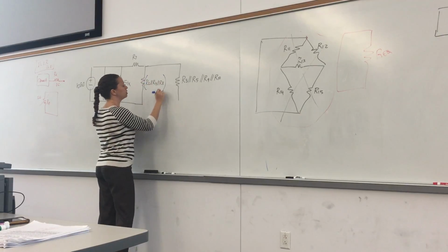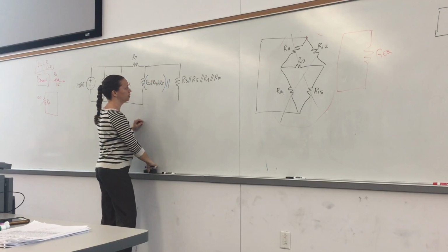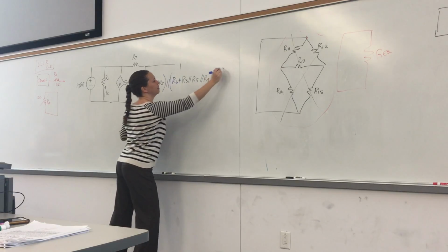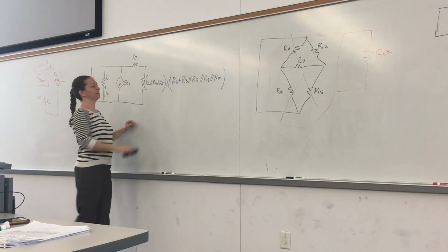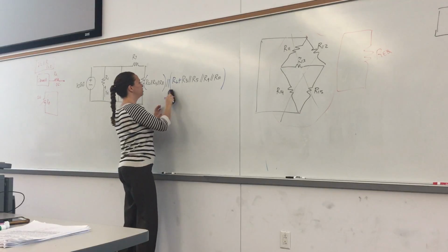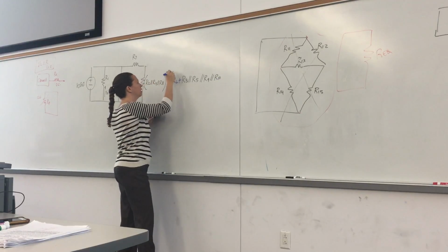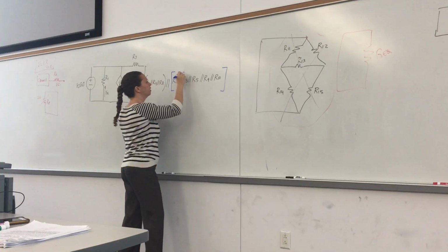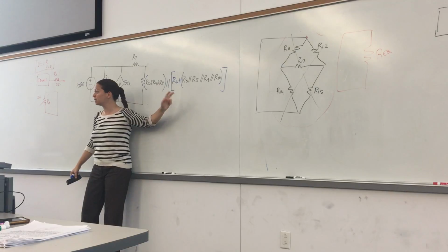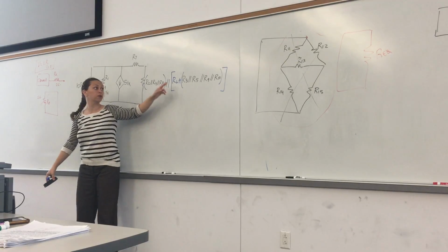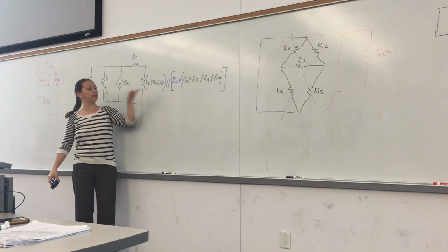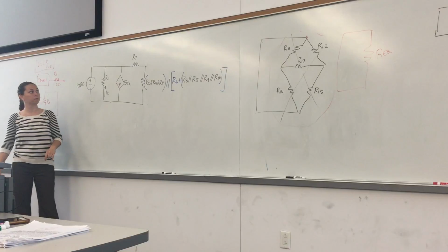Okay, so this whole thing in parallel with, look what I'm going to do. You can't do that. Okay, so R6 and parenthesis error, here like that, right? You are not adding 6 and 3. Be very careful with the parentheses when you are doing those calculations. So R6 in series with this whole parallel combination, which is in parallel with that resistor here. Okay?